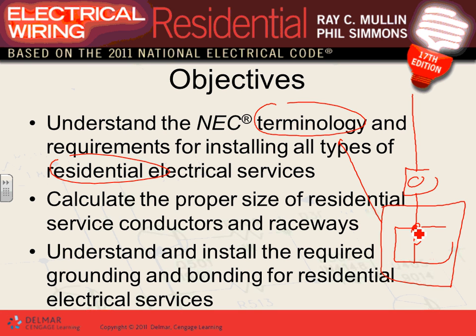We will get into the proper size, guys, for residential, since we're doing residential. So we're going to have service conductors coming in with a raceway. How do you size these? You guys already sized this, a couple of examples for me. I tested you in test number 1. We gave you a couple of amp sizes, and you went to Table 310.15(B)(7), I believe, and you sized all your conductors for it. So we're going to focus on that one.